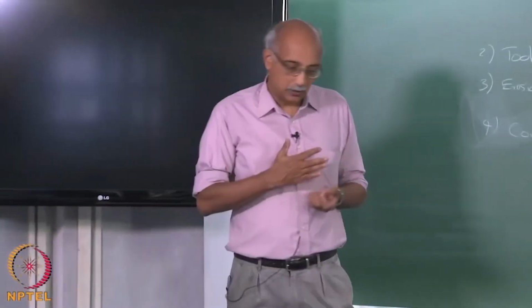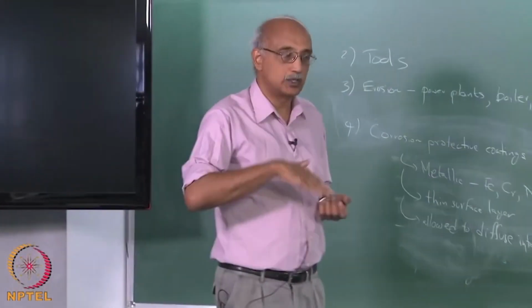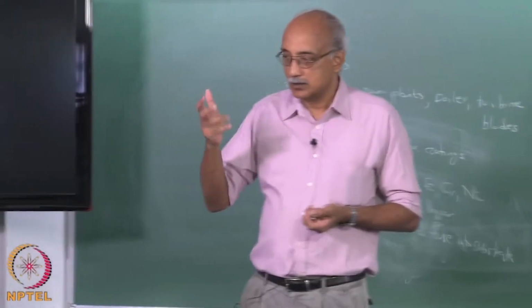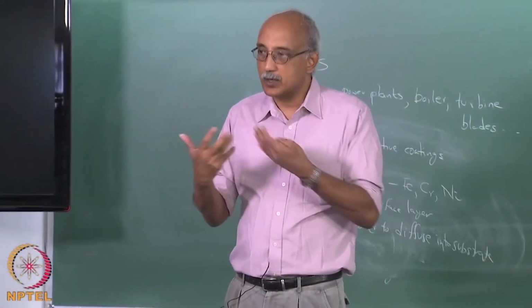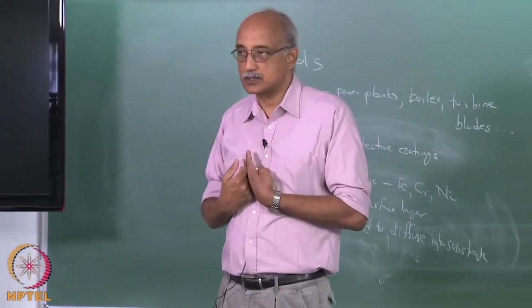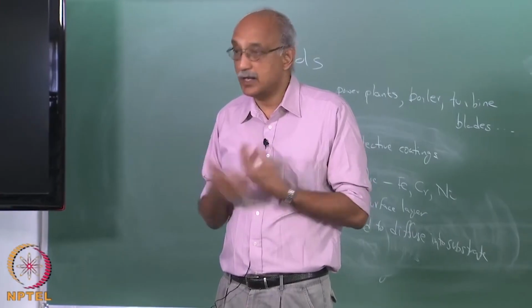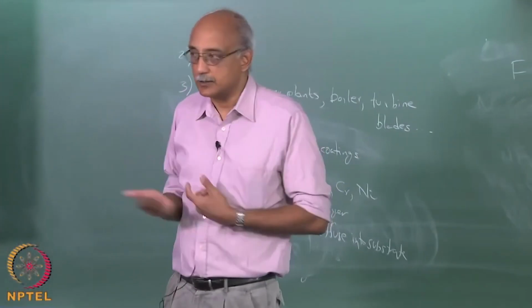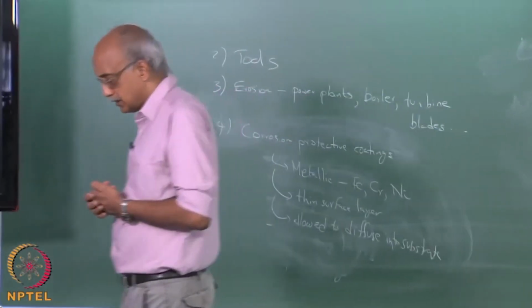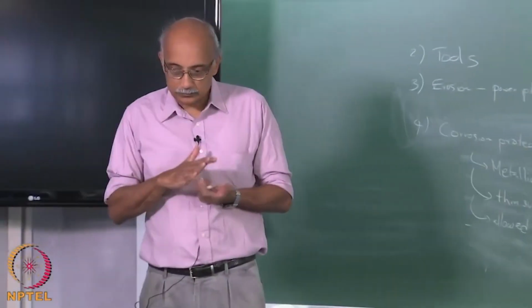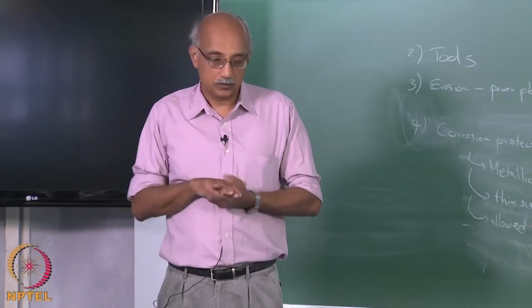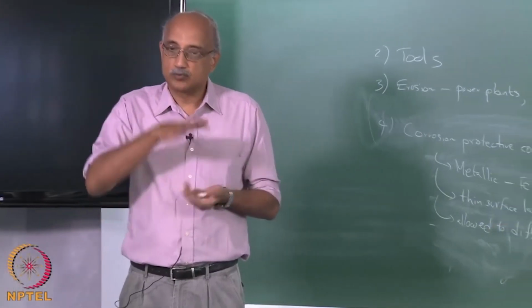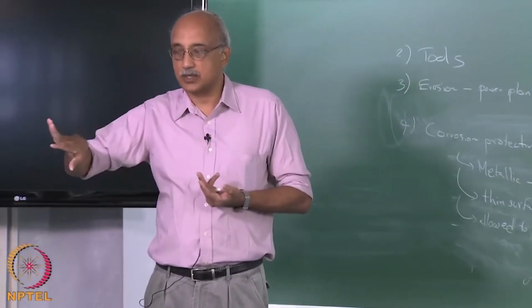And as this fluid passes over the bed, the metal particles will react with the corrosive gases and form halides. So, for example, Cr will form CrCl3, and then these gases, now the halides for example, are flown over the substrate that you are trying to coat.